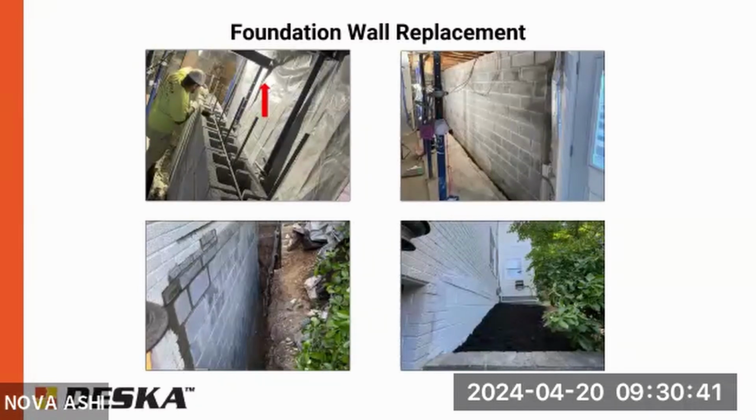Right, the question was, does it need to be brought up to the new code? If you're replacing something, generally it needs to be brought up to the new code. If you're repairing something, the original structure doesn't necessarily need to be brought up to the new code, but the repair does need to meet the code. When you're talking about steel beams or carbon fiber, for instance, carbon fiber is ICC certified, and the building departments will generally check to make sure that whatever you're doing is ICC certified, or it'll go through an engineering review to make sure they find it acceptable.